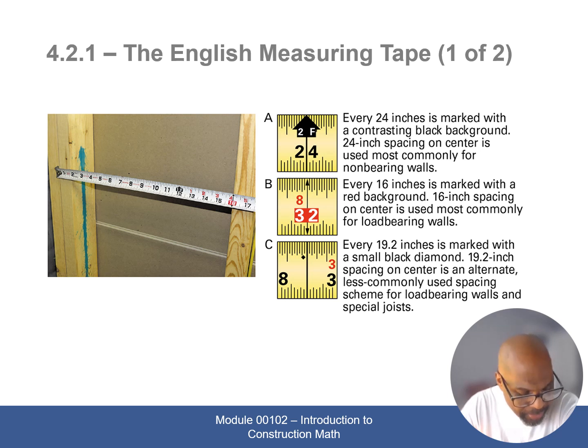Lay your tape on, let's say, a joist or a top plate. You can just use your carpenter's pencil and mark it very quickly without physically trying to measure everything, as it's marked for you already. Same thing like the 16 is marked for you, or 32, or every 16 inches on center, or every 24 on center. It will be marked.